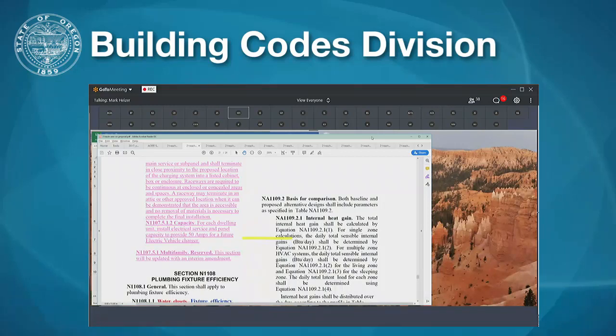So that's why I'm trying to be clear that there are certain chargers that would need a 50 amp breaker, but are running more like 40 amps and then have the ability to go down to 30, 20. You can selectively pick how much charge you can do. Just trying to clarify whether that's the actual draw load of the charger or the breaker service size for it.